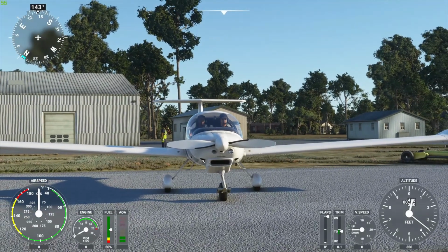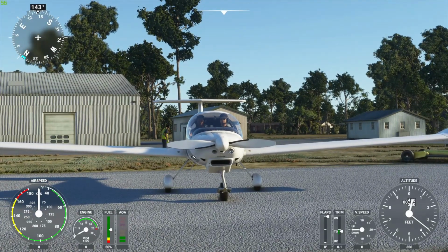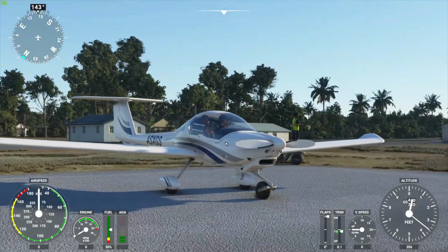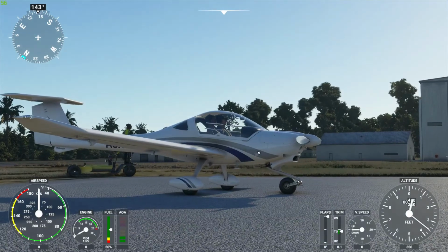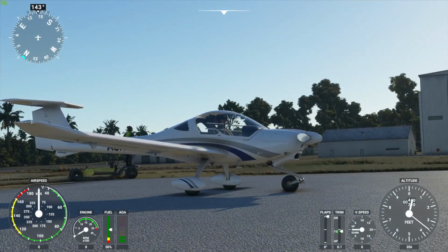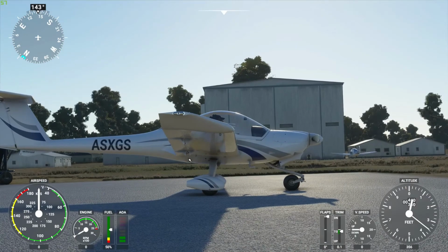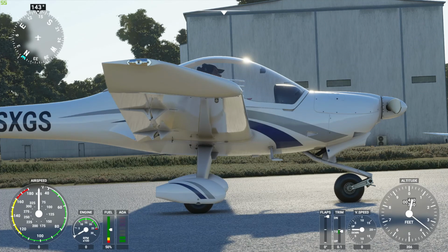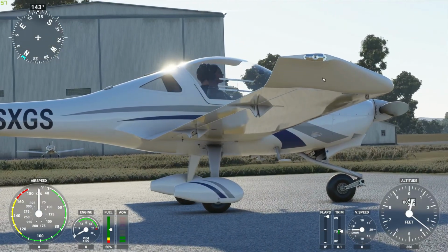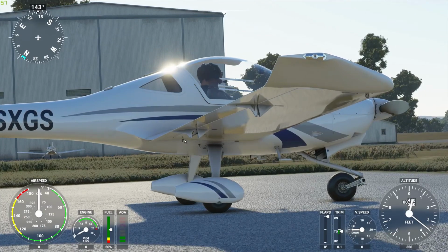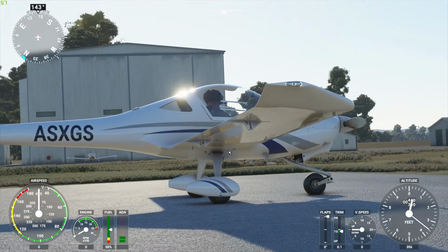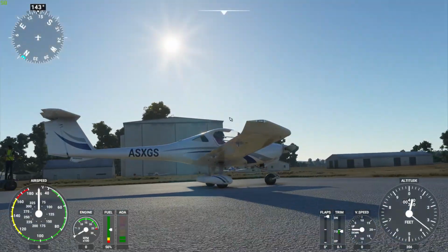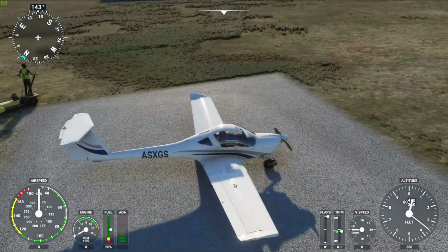Quite a few little air scoops and things to cool off accessories generally. Alternator, oil coolers, the oil cooler will be under this one, and that's about it. This is probably just an air vent, and we can see these are the two flat brackets on each side. Probably fuel drains. That's a brake line. Tie down ring. These are our other right nav light. Sorry, this is just an overflow vent for the fuel. And that's about it.